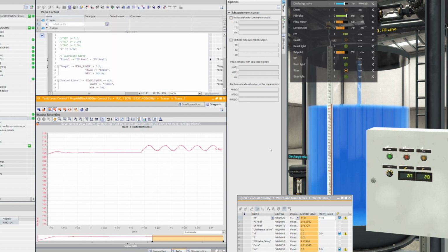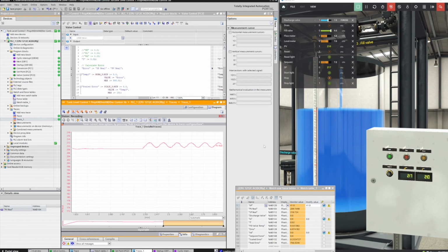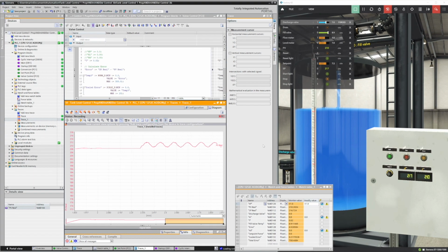To do that, we need the integral part of the algorithm to be introduced. However, take note of the gain value when oscillations occur, as this is known as the ultimate gain, and the time between the oscillations is known as the period. We'll come back to these numbers when calculating the initial values for Kp, Ki and Kd.